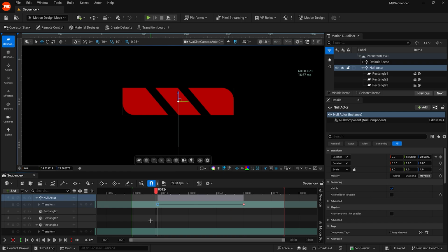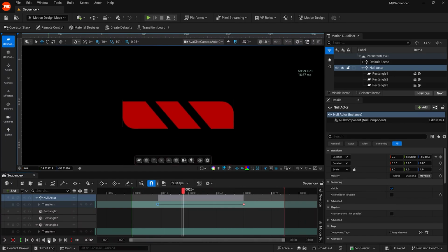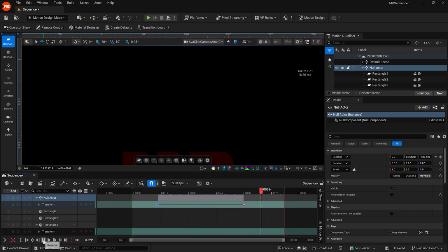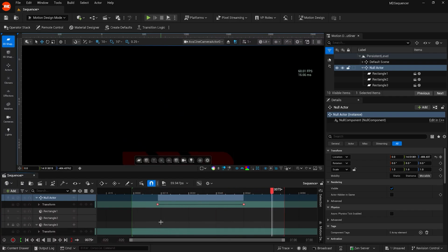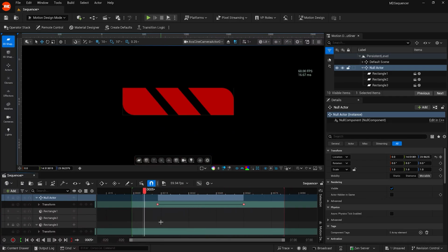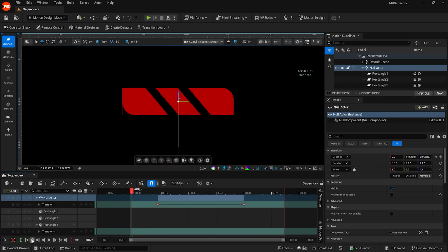Right at this point, the transport controls located at the very bottom right are one of the most important areas. Play, pause, and reverse are the primary functions. You can start your animation, stop it, or play it in reverse. At the same time, you can also use the spacebar as a shortcut for play and pause. The other standard transport control settings are the to end and to start buttons. If you want to move frame by frame, you can also use to next and to previous.